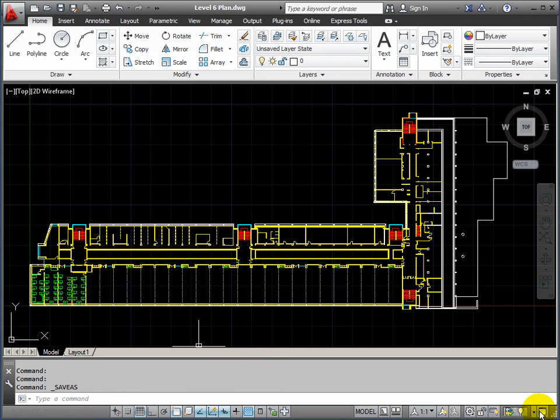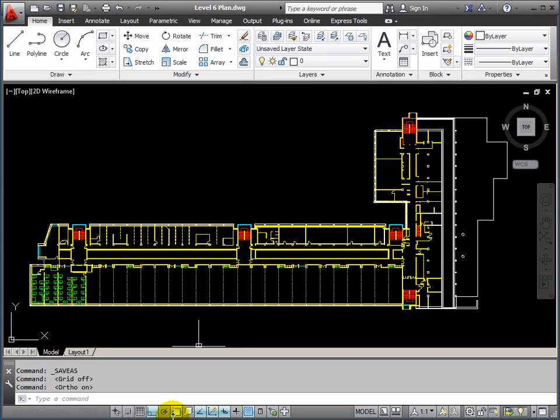Okay, below that we've got a kind of helpers area of the software. Now as AutoCAD gets older, it introduces different methods of working, and that's what most of these icons represent, different methods of working the software. Now for this course I basically only need access to the orthogonal and object snaps. This controls the direction of lines and movement, and the object snaps control the accuracy, so that if I want to draw from the center of a circle, I can do that accurately. So these are the only two I want active, so I'm going to turn the rest off.